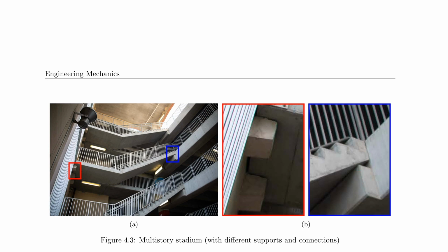You have one on each side. And what you cannot easily see in these images is that there's also a neoprene pad or something else underneath here, because engineers would never allow the concrete to just sit on top of the concrete. There has to be a friction barrier or something that allows friction or motion to be easily overcome. And we talk more about this when we talk about the degrees of freedom.